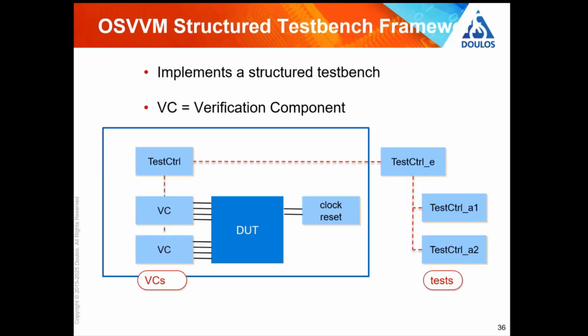So if we look at some actual, oh no, sorry, apologies, I missed one. So here's a diagram of the verification framework parts. This is the test bench Lego idea. What I've been calling a BFM or a driver or a monitor, this methodology calls a verification component, VC. So those VCs on those diagrams are the BFMs. They are generating the ones and zeros that the DUT understands. And this block there that says test control is the test. We'll look at that in a minute.